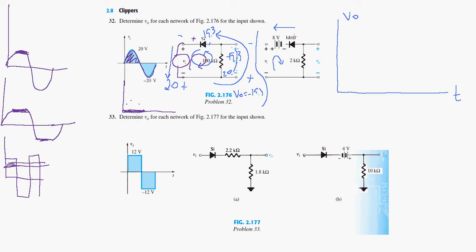And also this diode here is ideal. An ideal diode doesn't have the 0.7 voltage drop, so it has 0 volts across it. It's just a short circuit when it's forward biased. And so on the first cycle, when the voltage is positive, this voltage will start at 0. When the voltage here is 0, we have a short here, and then 0 will appear here, and then we have 8 volts here. So this 8 volts will forward bias the diode here.